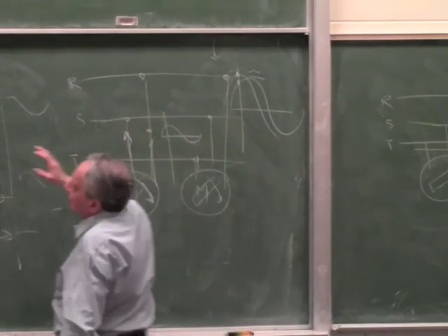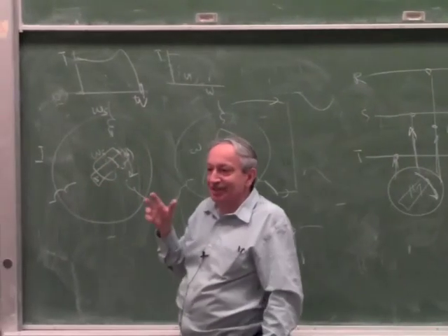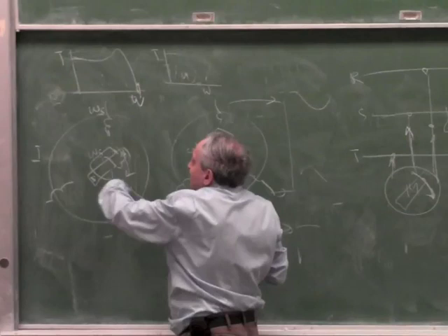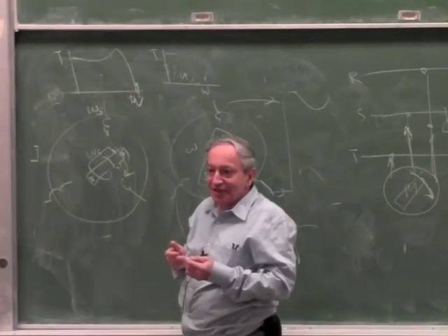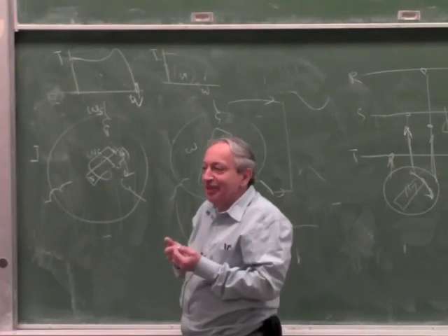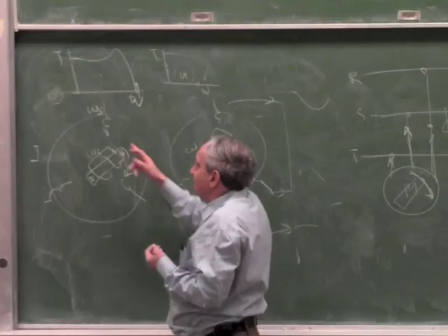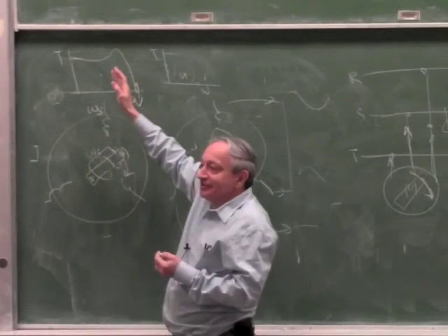So the same argument works here too, but instead of a power angle, you have to reverse the slip. You have to make this go faster than the rotating field. Then there is a slip, there is induced current, but the induced current is trying to generate an EMF which is actually leading in phase, and because the EMF is leading in phase, the current flows backwards.